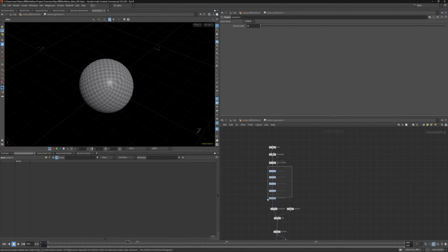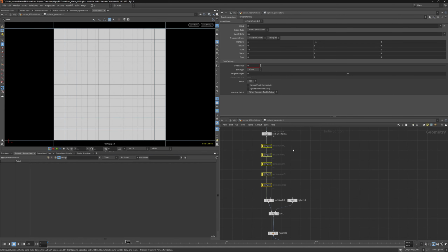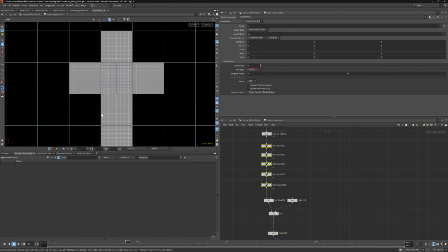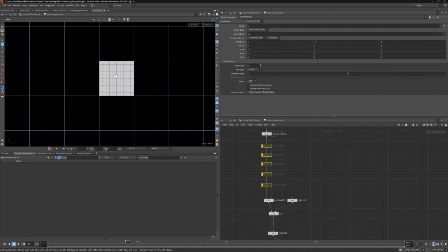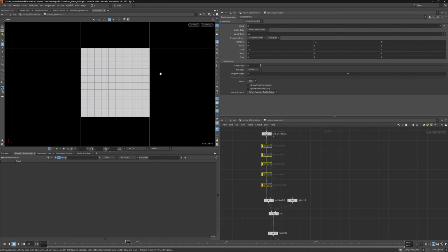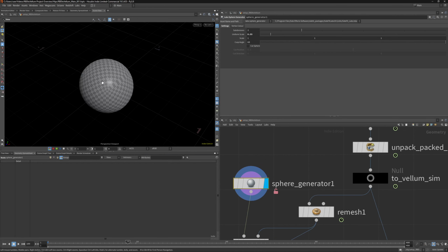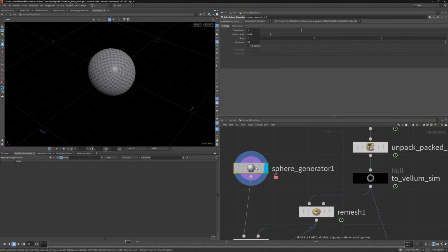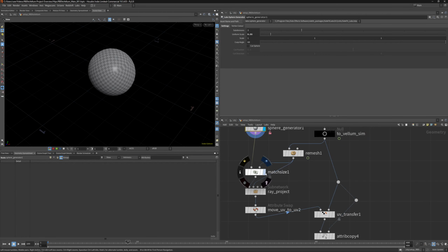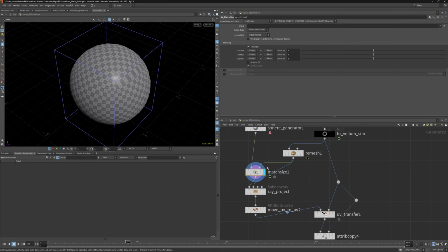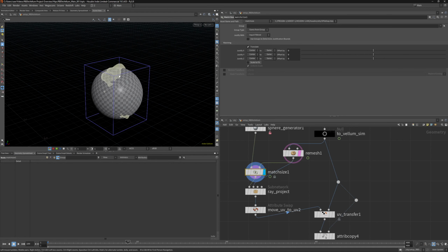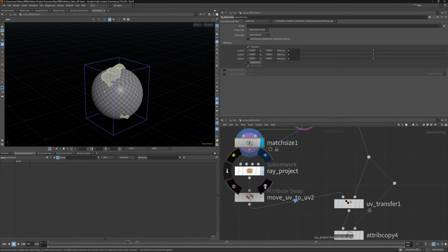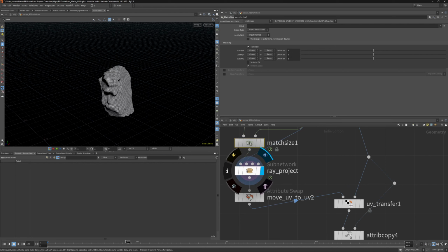And inside I'm just removing those nulls. If you enable them, you have UVs like that. I didn't want that. I just want stacked UVs for each side of this sphere. This is basically to have a tileable map applied to the sphere at render time. Then I'm matching size, as you can see, with these rocks. Then I'm using this array project. This is quite easy.